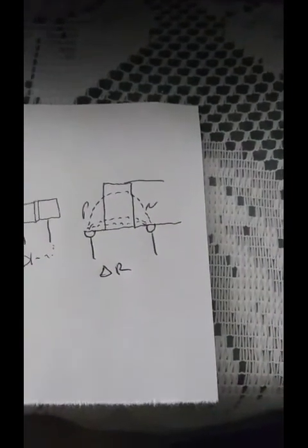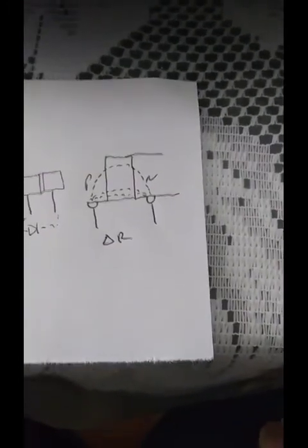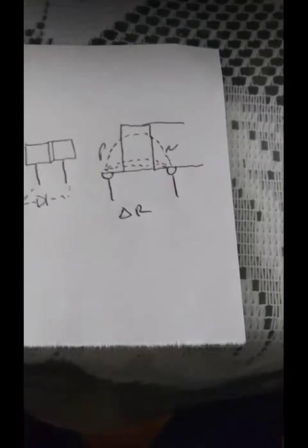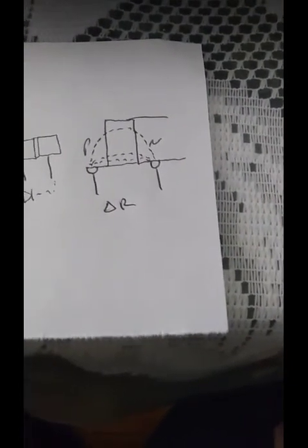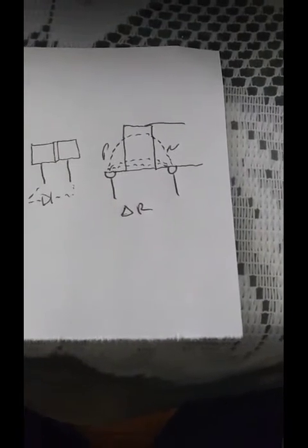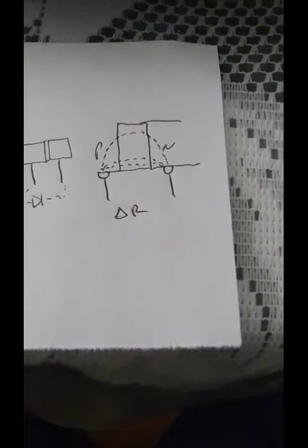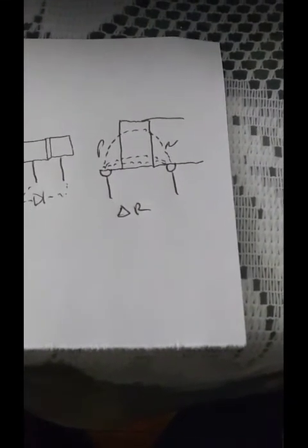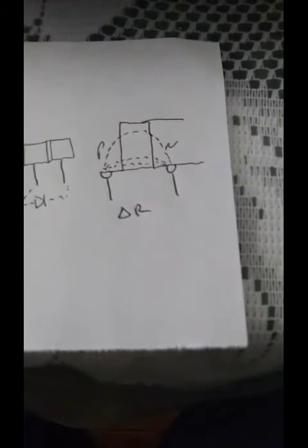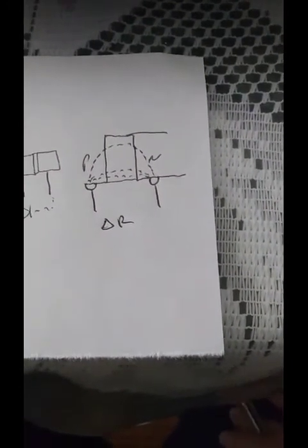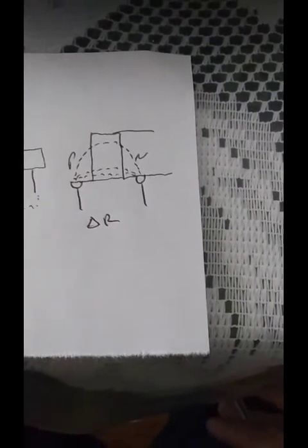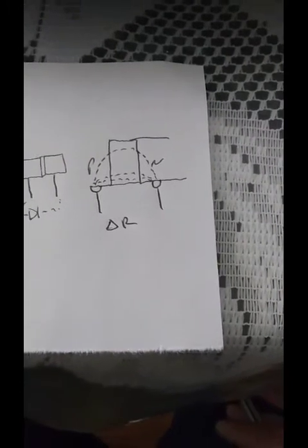It's a non-linear feature. That doesn't happen in vacuum tubes, because vacuum tubes are not solid state, they are electron coupled, and no such thing exists for the most part. It may exist in a small way at the elements, but probably not enough for mixers, which is, I think, the reason this couldn't be done with vacuum tubes until semiconductors came along. When there's sufficient current flow, the diode conductivity tends to become linear, and that defines a linear region in which mixing does not occur.